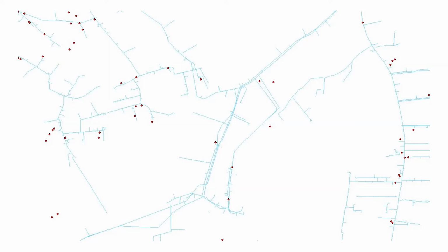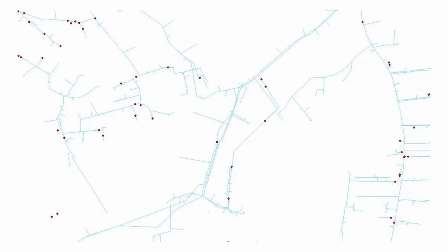And so what we were able to do is use the information from the GPSing of breaks to fine tune their map, and also do some estimates regarding how much pipe might actually be missing. So we did a query where we essentially said, okay, take every break and snap it to the pipe that's closest to it within X number of feet. And you can see that a lot of these breaks right now are well away from a piece of pipe. So we did that, and we got a slightly different map, and we're able to do a similar analysis to the one I showed you before to figure out which pipes had the most breaks.